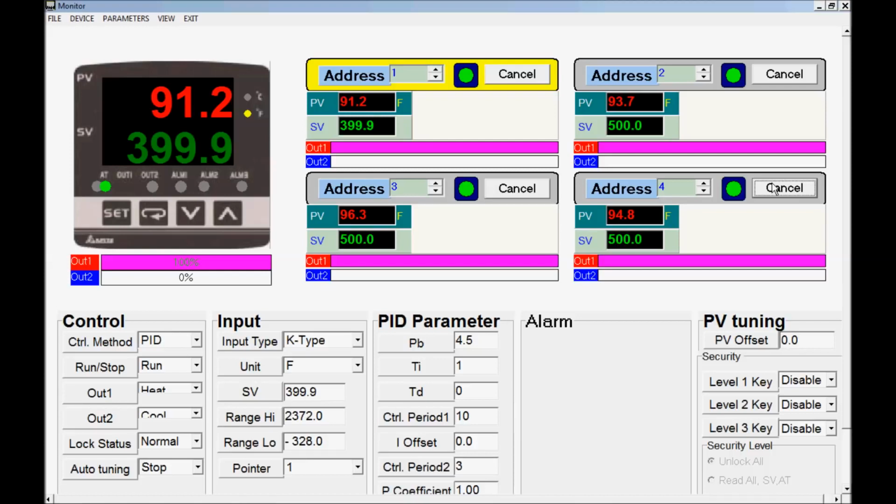Okay, we're connected with our controllers, and for our application in thermoforming, we typically use these in thermoformers and extruders. What we are going to do is set these up, and there are a couple of different settings that we can use on here. We can use it for PID, on off, manual, and ramp soak. We use PID, so we'll leave it for PID.